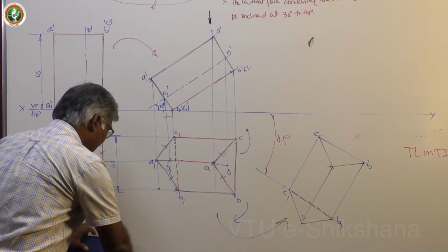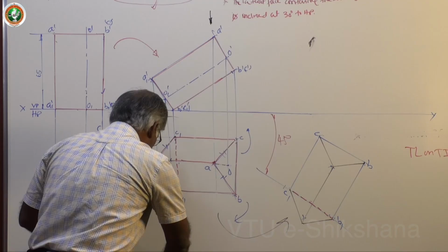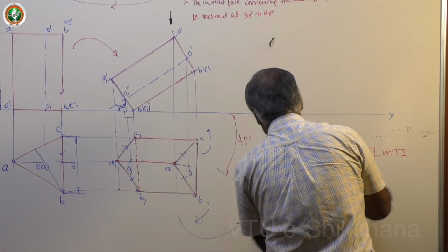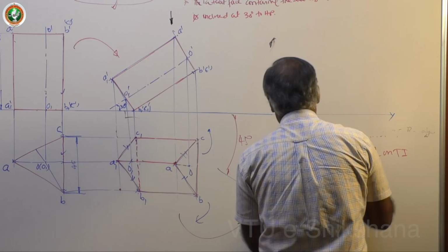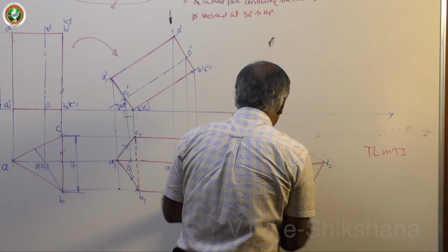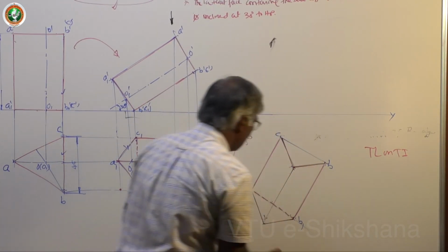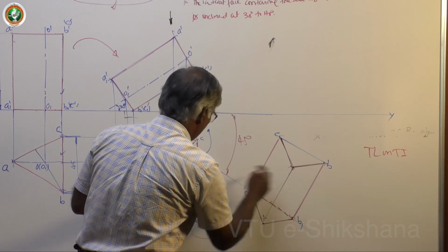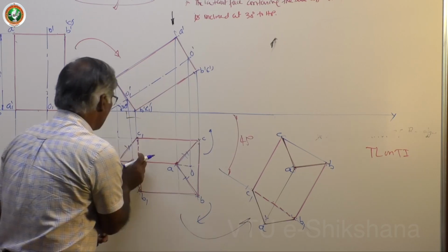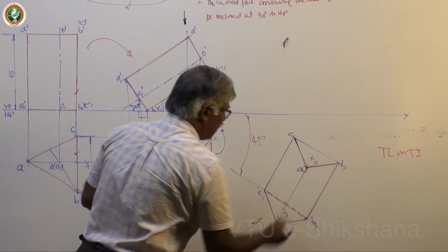Now how to project? Basically the projections should be done carefully, particularly in second figure top view. There are a lot of inclinations and also coinciding lines, etc. Okay, so must carefully do it. What you do is, project first base corners. Let me name, this is A1 B1 C1. At the same time you take this distance also, axis distance O1 and O, that's all.